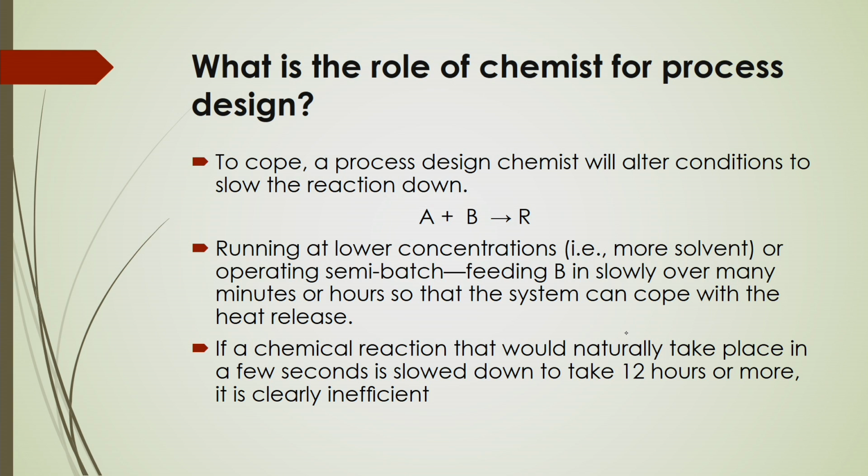Now, if you are using a lower concentration of any reactants, then to lower the concentration you have to use more solvent, or you operate a semi batch process where the feeding of any reactant, like here B, is done slowly over many minutes or hours, so that the system can cope with the heat release. So, if a chemical reaction that would necessarily take place in a few seconds is slowed down to take 12 hours or more, it is clearly inefficient.